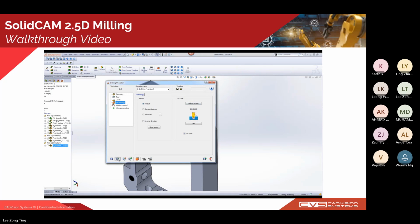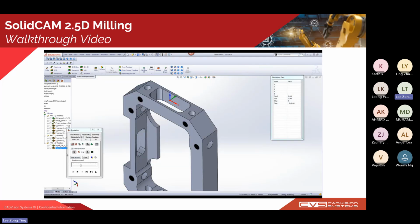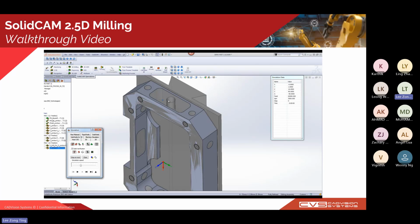Okay. And you can see that the drill actually comes before the pocketing operation itself. So it will automatically arrange the drill before the pocket itself. And after that, you can go ahead and simulate the pocket operations. You can see that actually there's already a hole in the middle before the pocket operations. So the mill can enter from the middle.